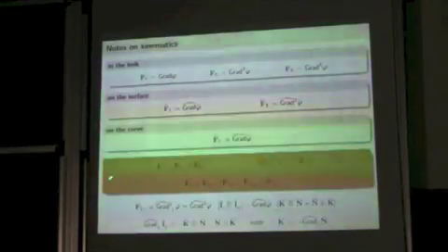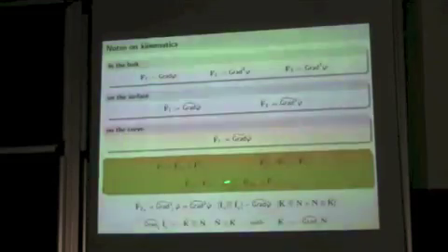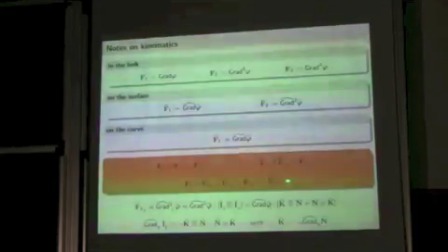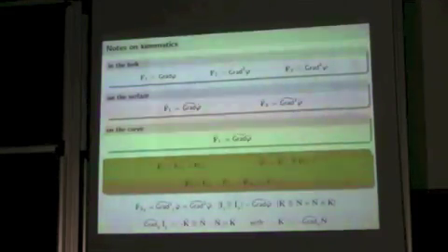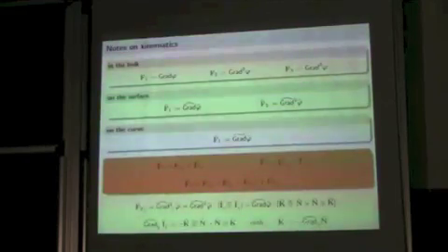I just want to add one more thing. If you decompose the surface deformation gradient to the tangential and normal part, you could also do the first gradient for the curve, so you can also decompose it to the tangential and normal part. But if you look at the second gradient of the surface deformation gradient, it has now 4 contributions. The first contribution is purely tangential, the last one is purely normal, and you see 2 mixed components. But the first one, which is purely tangential, if you calculate it and write it down, you see this structure. So it has normal in it and it has also curvature in it.